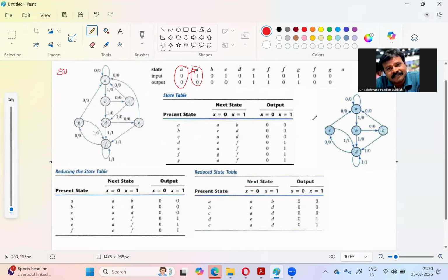From the state A 1/0, it will go to state B. So we draw another new state, and then here we are having that edge. So input 1, output is 0. Now from B, by 0 input, it will go to C, the output is 0. So here input, output, then you transit to C, A, B, C.